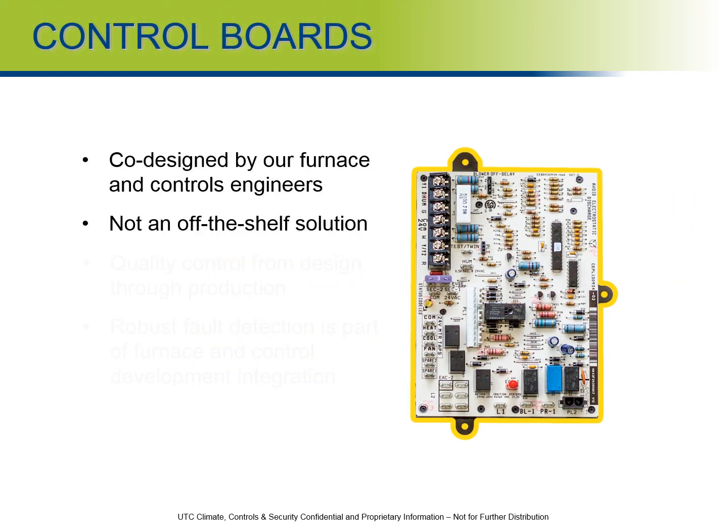First thing we'll start out with is control boards. By now, guys, at this point you should know control boards, there are no universal replacements. Most control boards now in the furnaces, specifically after the FER rule came into place, are proprietary to each furnace. So there is no off-the-shelf universal solution or replacement for these furnaces. They have to be OEM replacements.